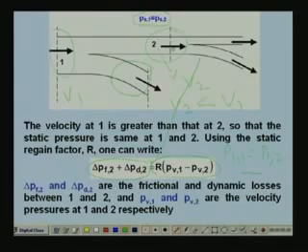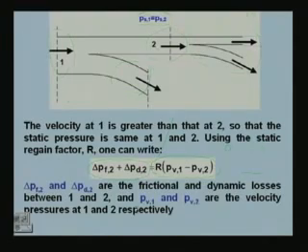So, what is section 2? Section 2 is nothing but the upstream for the next downstream section and the branch. Okay. So, you keep the static pressure here equal to static pressure here. Similarly, if you have further branches and downstreams, again at this point also you have to select these duct dimensions in such a way that the static pressure in the downstream will also remain same as that of the upstream. Okay. So, this is the static regain method. Okay.